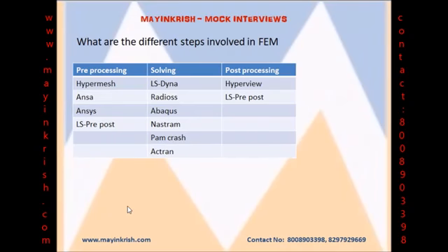Finite element analysis comprises pre-processing, solving and post-processing phases. Discretizing the part, that is meshing the components, assigning thickness, materials, loads, boundary conditions, removing intersections, penetrations, and screw connections, spot welds, is involved in the pre-processing phase. Hypermesh, ANSA, ANSYS and LS-PrePost are the best pre-processing tools.